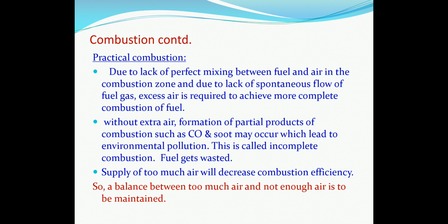Let us see what partial combustion is. Due to lack of perfect mixing between fuel and air in the combustion zone, and due to lack of spontaneous flow of fuel gas, excess air is required to achieve more complete combustion of fuel. Without extra air, formation of partial products of combustion such as carbon monoxide and soot may result, which will lead to environmental pollution.